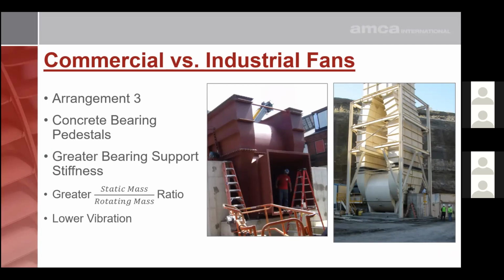The concrete pedestals provide superior bearing stiffness, support stiffness. Heavy concrete pedestals have a high static to rotating mass ratio, thus they reduce the impeller response. A fan with a large static to rotating mass ratio, again, will be less sensitive to imbalance. Ultimately, lower vibration and increased bearing life is the goal here and what's expected out of this arrangement.